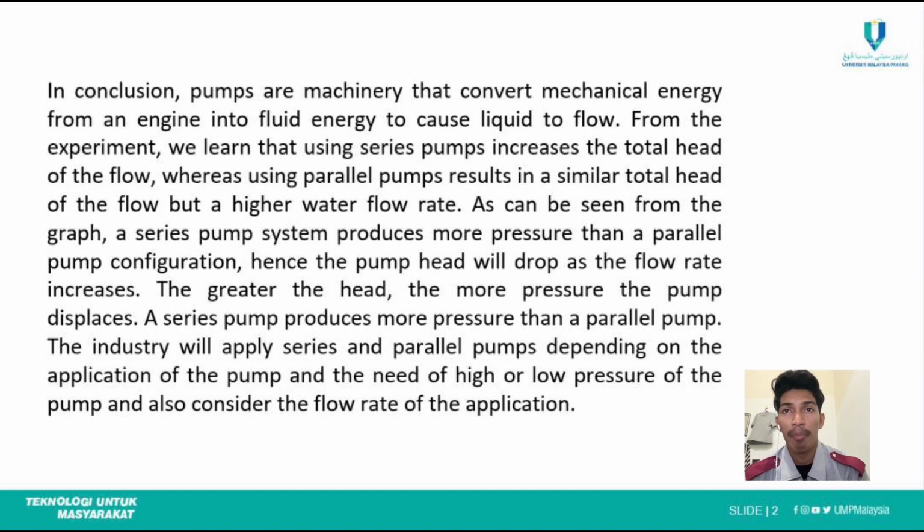The industry will apply series and parallel pumps depending on the application of the pump and the need for high or low pressure of the pump, and also consider the flow rate of the application.